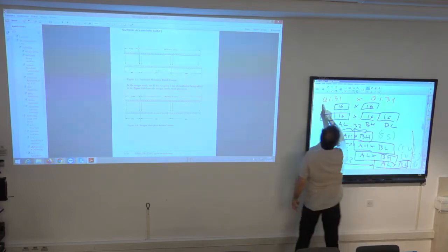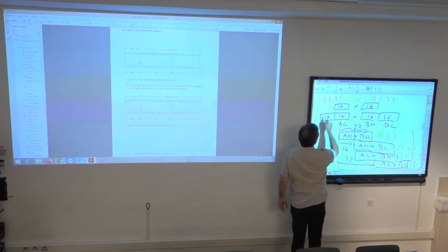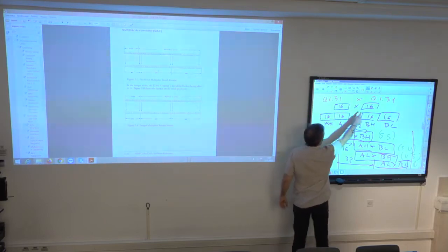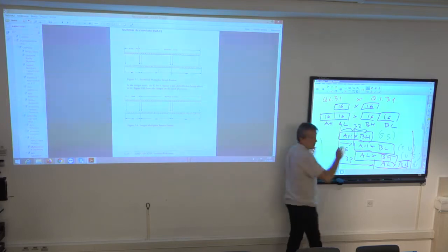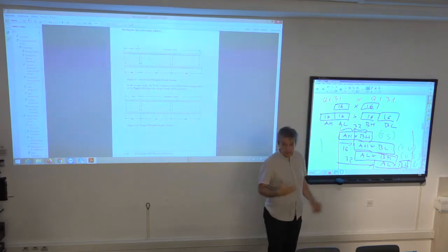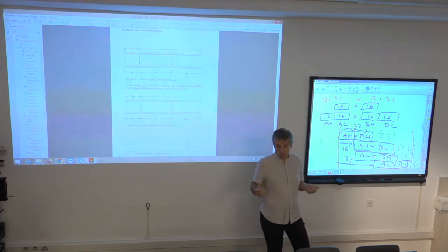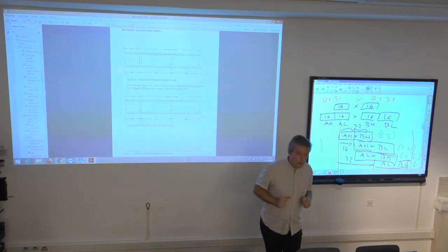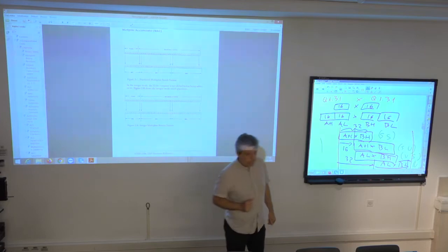So instead of having the decimal point after the first bit, the decimal point can be on the right side of the register. And that means that I interpret the data as integer numbers. If I want to operate the multiplier in this integer mode, I can. I simply have to set one bit in one of the control registers, and after that, instead of interpreting data as fractional numbers, it interprets them as integer numbers. Okay? Okay, let's make a break. Then we will continue.